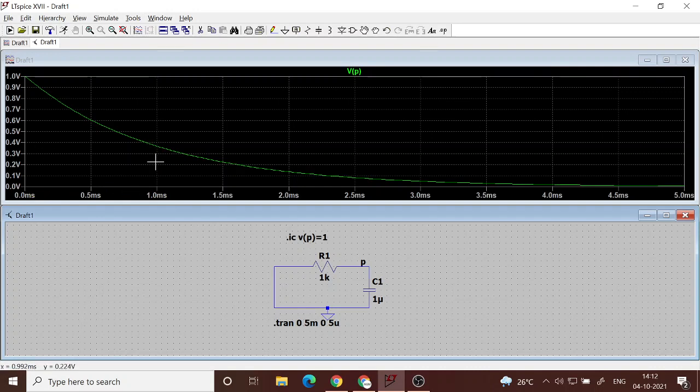And if you look at the expression for this decay, you can evaluate the response of the circuit by using the Laplace transform method, which I taught you in signals and systems. Since the input is 0, the Laplace transform of the input you write as 0. There will be only one term, which is due to the initial condition, which is basically Vc of 0 minus. So that will have some response like this.